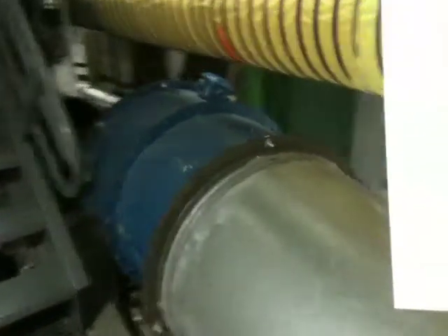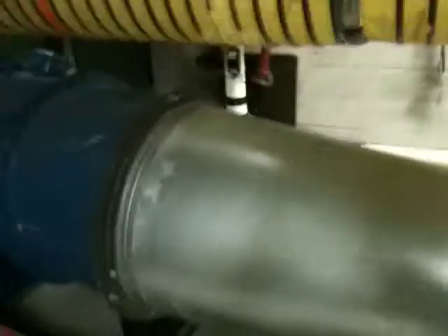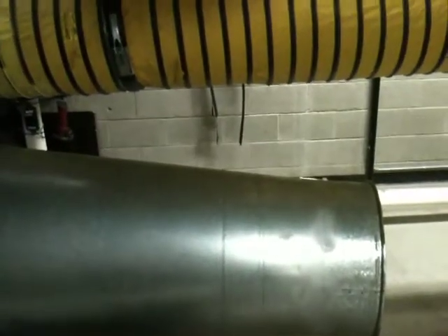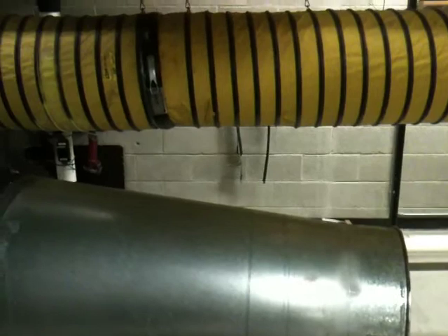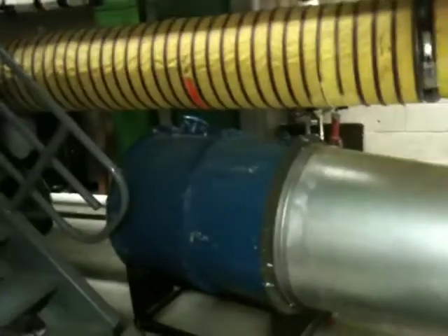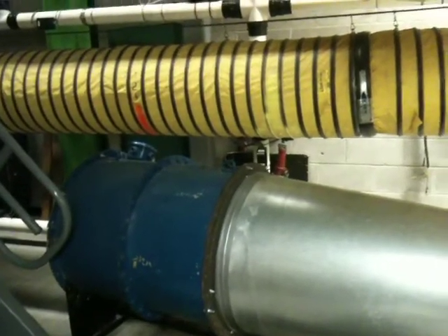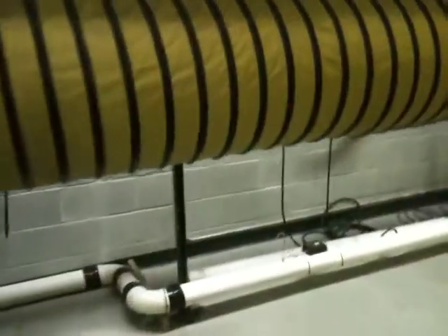Around the corner here is the first of 2 5 horsepower fans that we have. And as you can see, it's got a larger rotor diameter than the 10 horsepower fan, so it's connected to the fan test stand with this conical adapter section here. So we'll do the same thing with this fan. We're going to use 8 different flow restrictions to record 8 data points, again at a low speed and a higher speed.